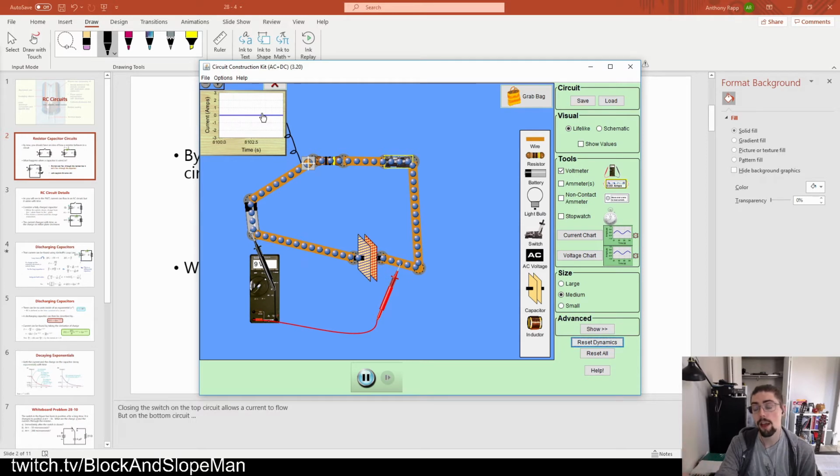As the capacitor becomes charged, as it picks up that potential difference, there's a smaller potential difference between the positive end of the battery and the positive plate of the capacitor. It starts out at 9 volts, and it gets smaller and smaller and smaller as time goes on until we approach 0. At which point, no more charge can move, but at the very beginning, we have the greatest current because there's the most force sending the charge along their way.